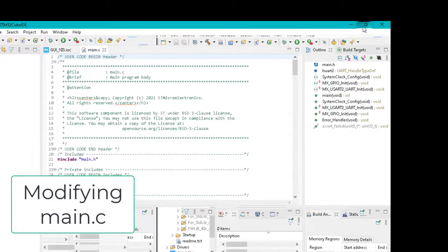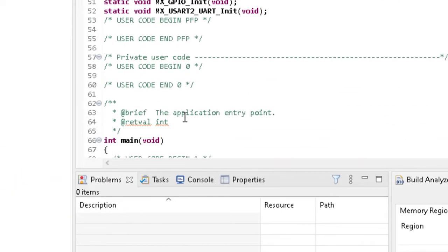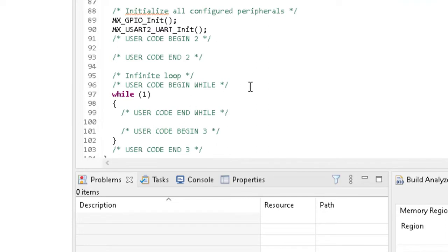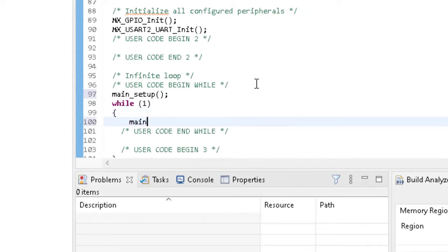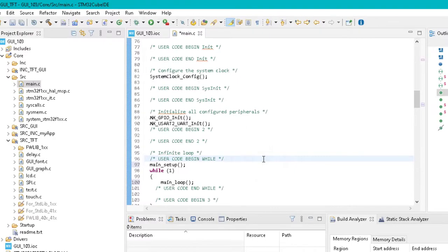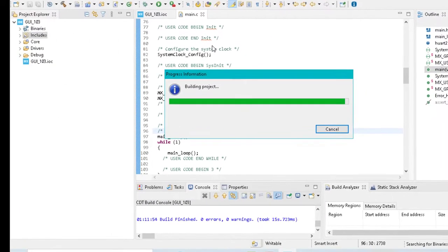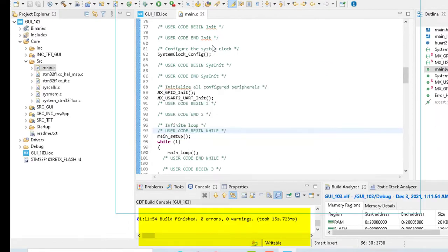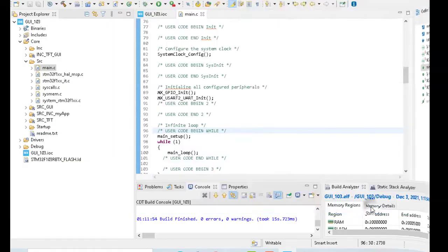And finally, we have to add some lines in the main file. It is assumed that in the main loop.c we have the functions for the setup and also for the periodic task, so we have to add its header file. You will have to modify this last function, and maybe also the setup, to operate with your own design. And it's ready to be compiled. It will take a long time, but with a bit of luck, we'll have no errors, and so it will be ready to be transferred to my microcontroller.